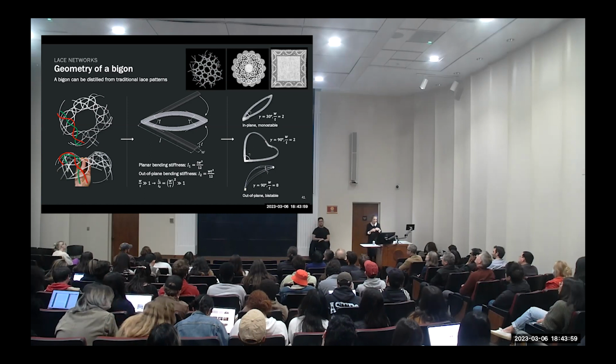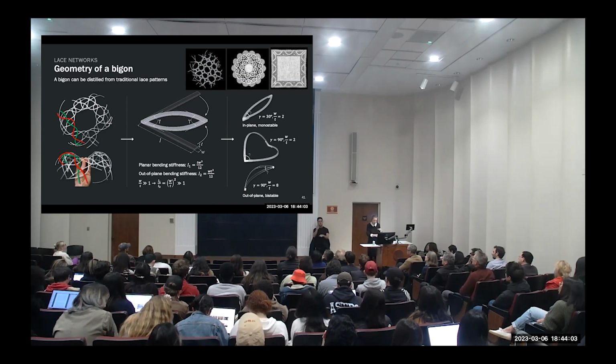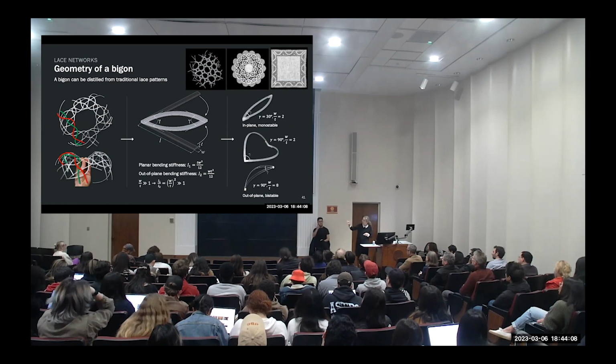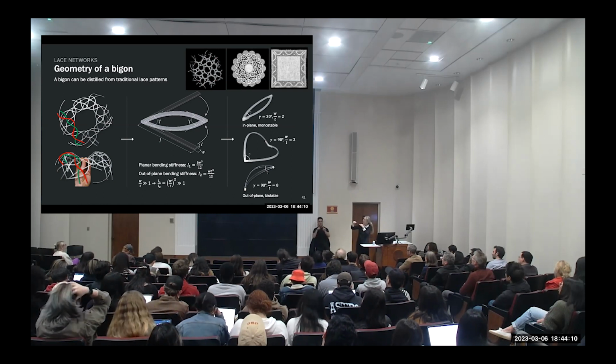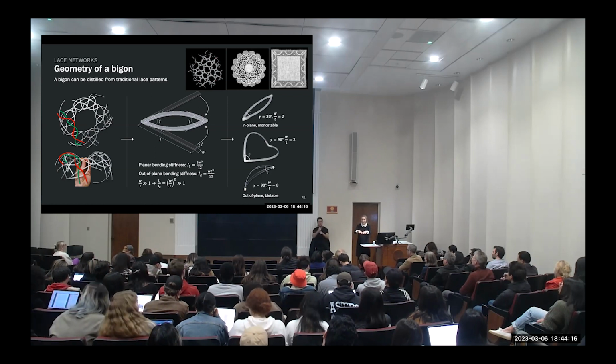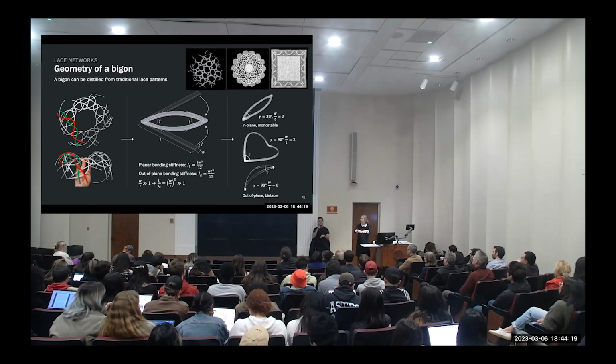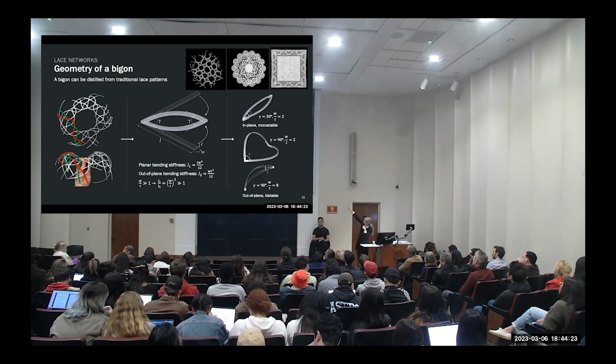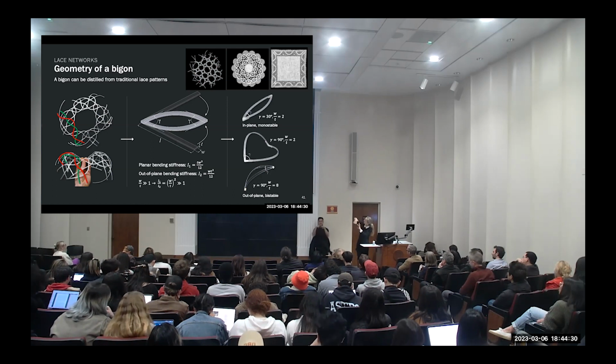And so we kind of figured out that at the smallest unit level, if you have two elements that are not circular, but that have a rectangular section, and you force them at a certain angle to be planar, we call that geometric frustration. They cannot stay that way, and they actually buckle out of plane. So in the right-hand column, you see one that's happily staying in plane, but as you start increasing the angle there at 90 degrees, it goes out of plane.